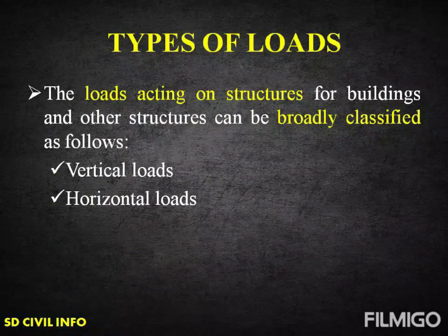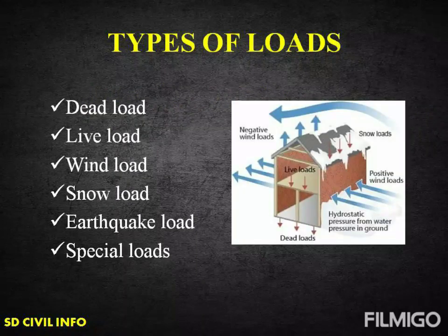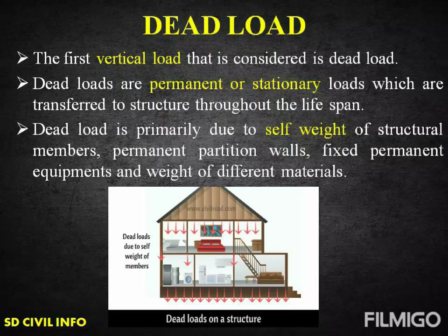The different types of loads acting on structures are broadly classified into the following types. They are vertical loads and horizontal loads. These types of loads include dead load, live load, wind load, snow load, earthquake load, and special loads. Let us see one by one.